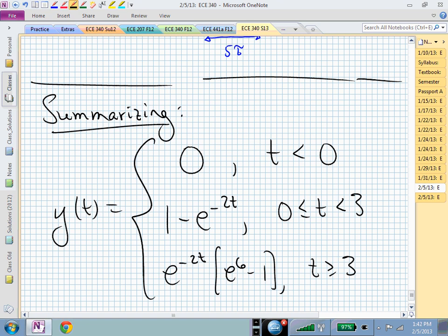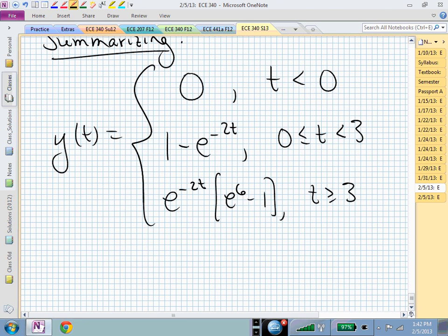And we had these 3 cases because f sub 2 had a finite duration, didn't it? And it wasn't too messy. But if we had one of those waveforms having many different pieces, then we might have a lot of different cases and a lot more lines to worry about for our expression for y of t. Question? So if that f sub 1 had been shifted into the negative axis to the left, then we could have ended up with a non-causal output y here.